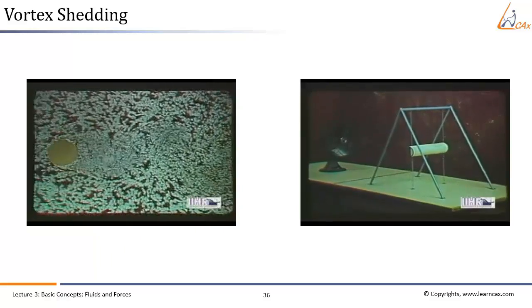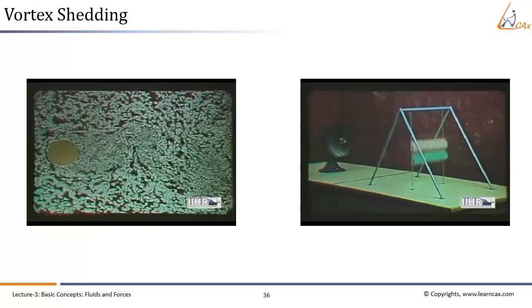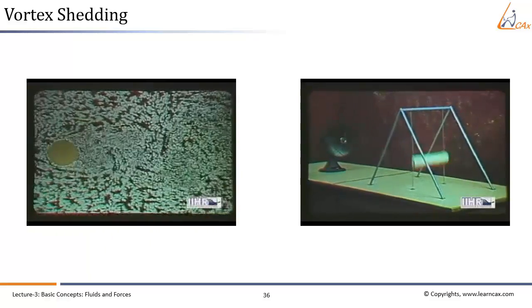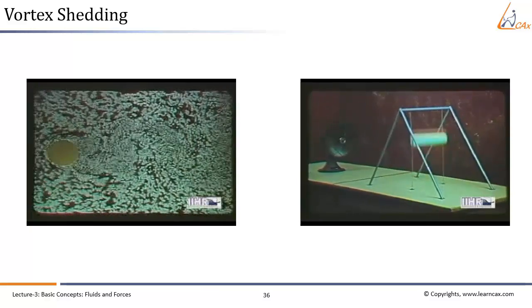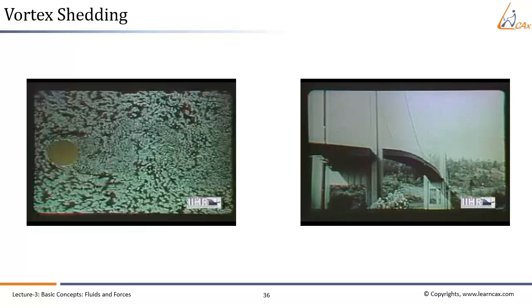The vibrations generated by vortices near the body may cause the body to resonate to dangerous levels if the frequency of the vortices is close to the natural frequency of the body. This situation must be avoided in the design of equipment that is subject to high velocity fluid flow, such as the aircraft wing and suspended bridges during heavy winds.